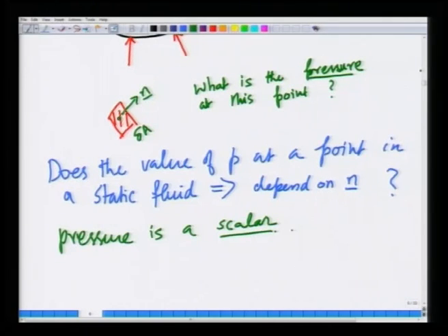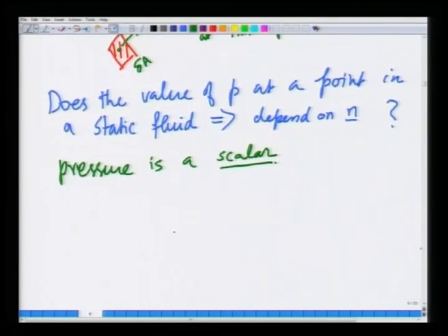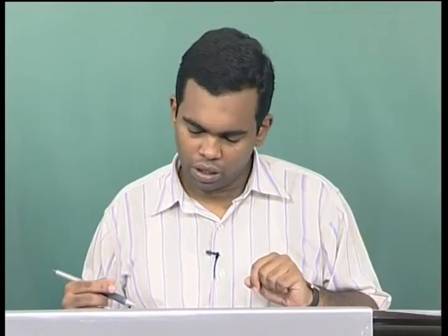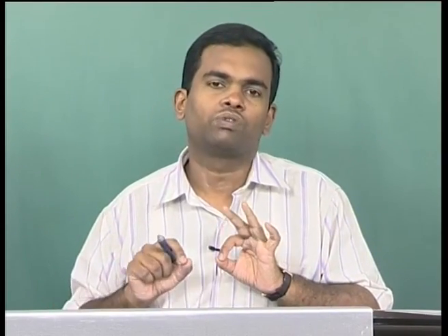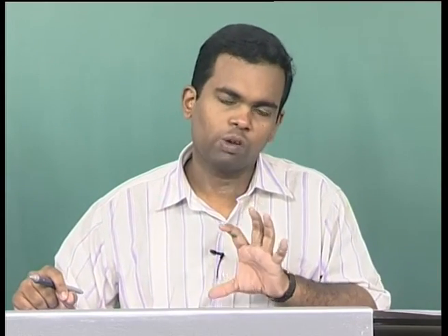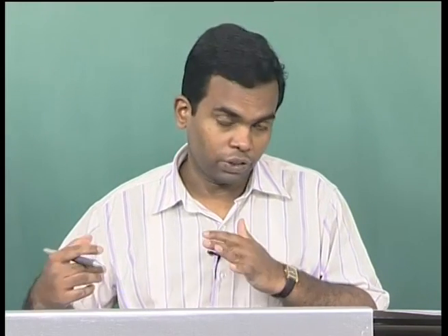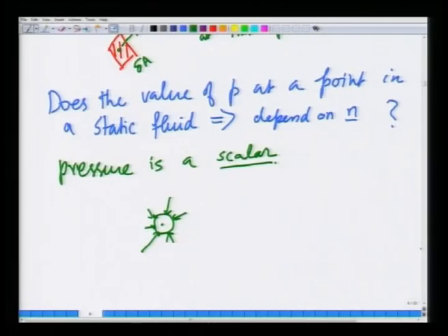That is, at a point, pressure is force per unit area. If you construct a tiny volume about a point, of arbitrary shape and orientation, at the surface the pressure is always compressive, always in the direction opposite to the unit outward normal. So pressure does not have a sense of direction at a point; it is the normal force per area on a surface of any orientation that you would construct about a point.